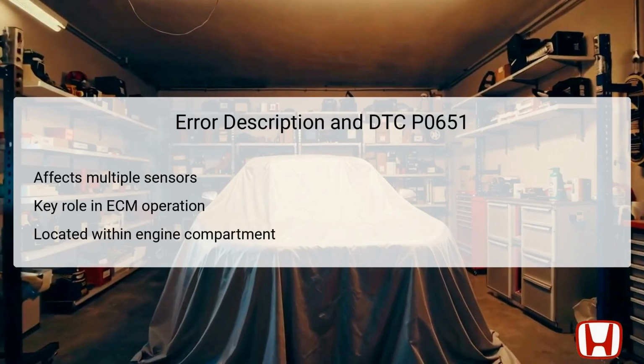The DTC P0651 is a fault signaling a malfunction in the sensor reference voltage, specifically a voltage issue affecting various sensors in the vehicle. The primary components involved include the APP sensor, AC pressure sensor, and FTP sensor, all crucial for the proper functioning of the vehicle's ECM.